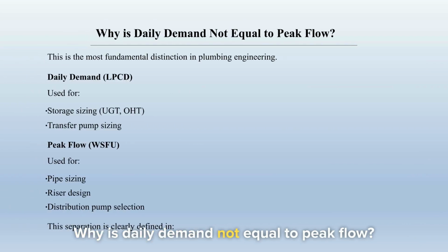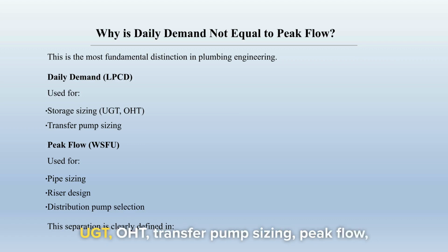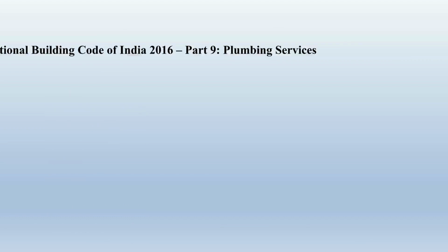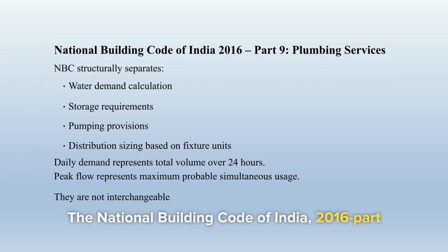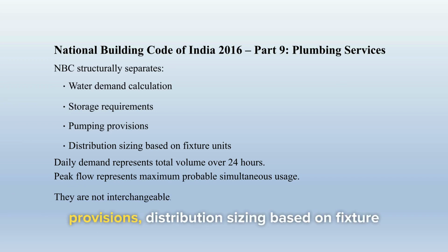Why is daily demand not equal to peak flow? This is the most fundamental distinction in plumbing engineering. Daily demand, LPCD, is used for storage sizing; UGT, OHT, transfer pump sizing. Peak flow, WSFU, is used for pipe sizing, riser design, distribution pump selection. This separation is clearly defined in the National Building Code of India, 2016, Part 9. NBC structurally separates water demand calculation, storage requirements, pumping provisions, and distribution sizing based on fixture units.